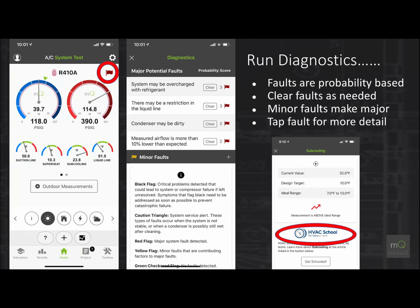There are 3 symptoms of that. But there are also 3 symptoms that there's a restriction in the liquid line. A restriction in the liquid line is a lot less common than an overcharge in the system, but it does have some similar characteristics. We also have 2 symptoms of a dirty condenser, and we have low airflow. So as we go through and check things, like if we check our condenser and visually inspect it and it's all clean, then we can clear that fault out, right?